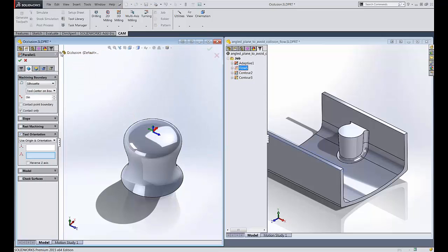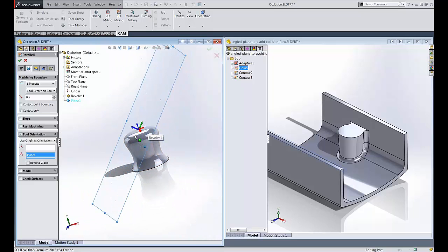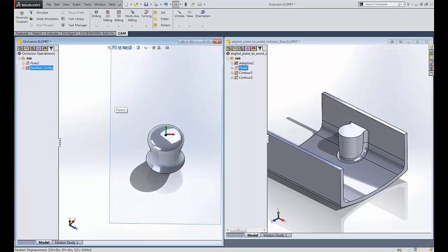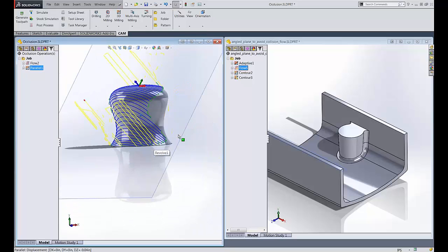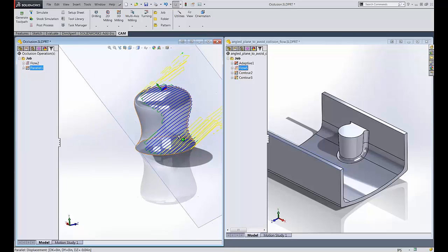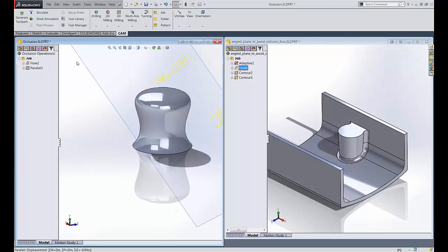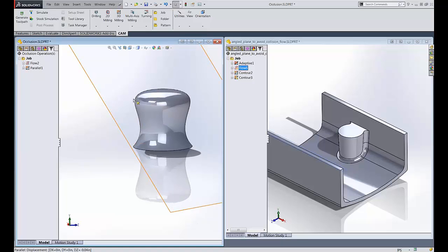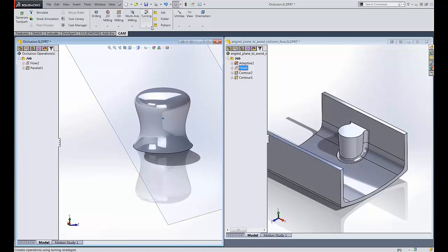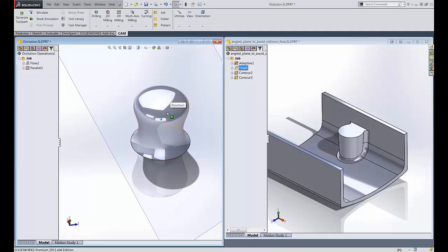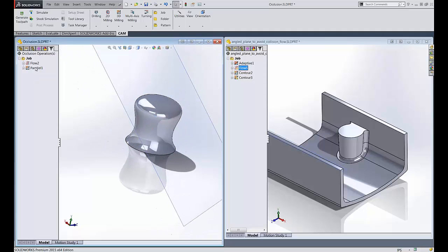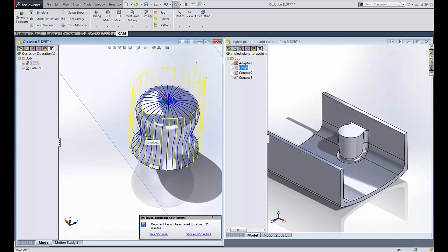So then you can use that plane to drive your tool orientation. You can see that it just picked the vector normal to how my screen was looking. But obviously, from any one orientation, you're not going to get complete coverage out of a projection-based toolpath on this. It just isn't going to happen. Therefore, I'm fairly confident that aside from using a T-slot cutter or a lollipop, multi-axis toolpaths are probably the only way you're going to machine this entire surface in one shot from one orientation. And that's because flow is not based on a projection.